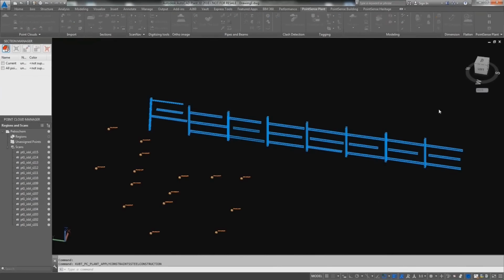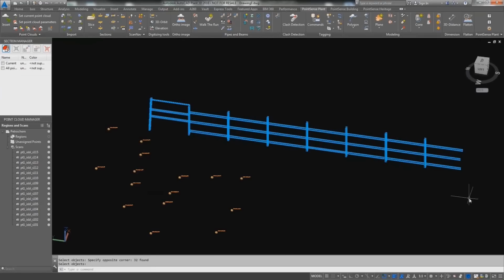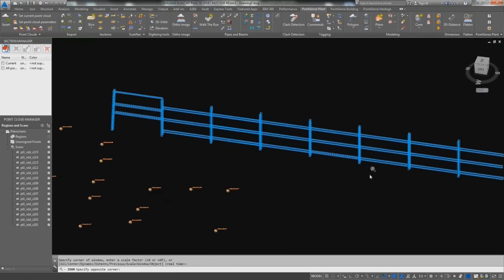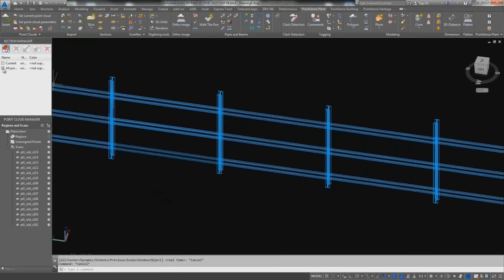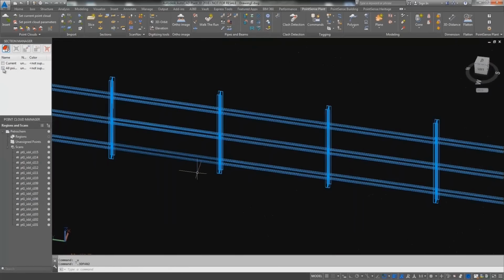This is where our Apply Constraints tool comes in and has a much better interface, lets you specify an angle and a distance tolerance. Then you can see all the pieces that do fall within that tolerance line up to each other. Now there are also separate ways to see how much things were adjusted to make them line up, so anyone who needs sort of an analysis, you have that option as well.